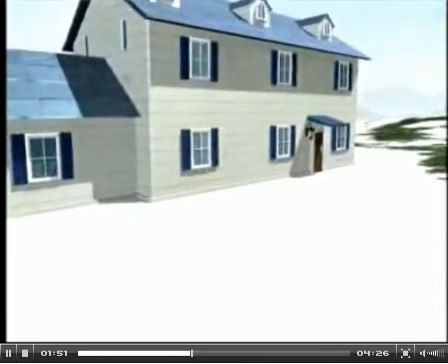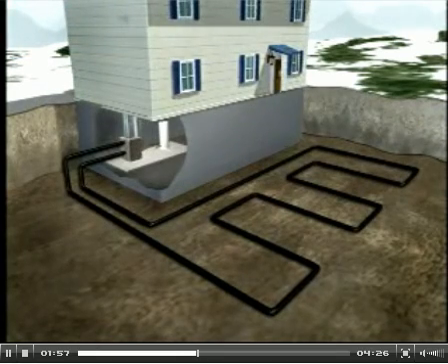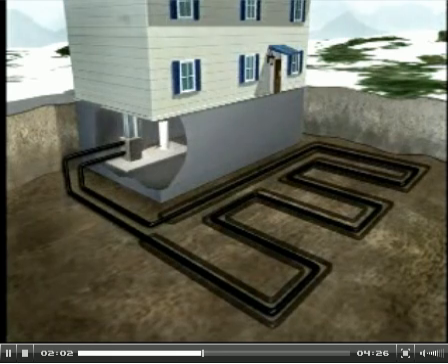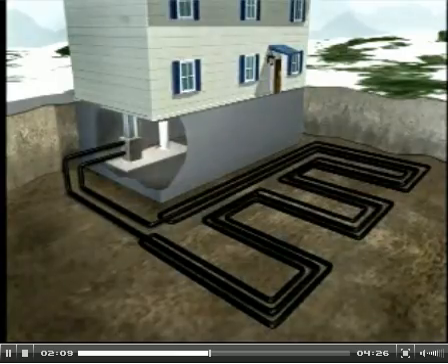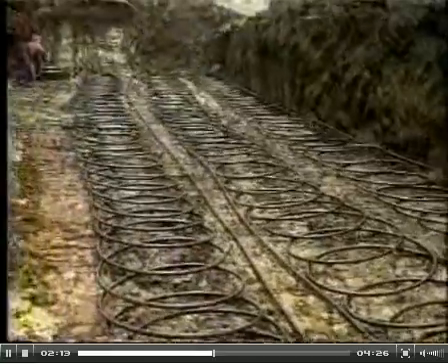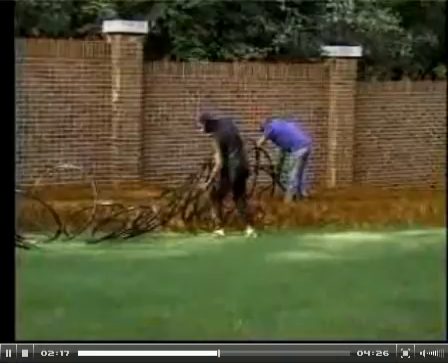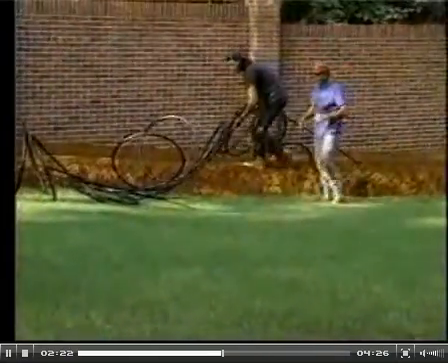In some installations, the pipes of a closed-loop system can be placed in a horizontal trench dug below the frost line. The number of pipes in each trench and the number of trenches needed will vary depending on the size of the geo-exchange system being installed and the type of soil found in the area. To minimize trenching, slinky coils, spring-like coils of polyethylene pipe, can often be used to increase the pipe surface area and thus the heat exchange per foot of trench.